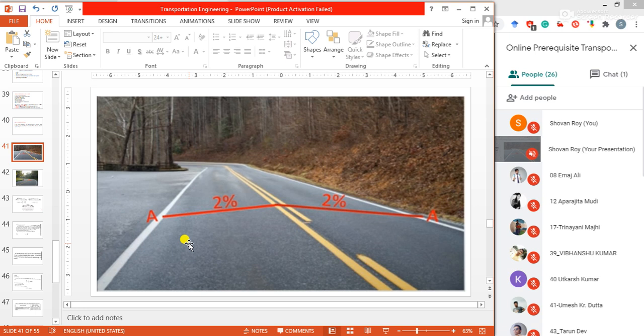So our work is how quickly we can drain off the water from the road surface. This is our main objective during road construction or pavement construction. So to prevent the entry of surface water into the subgrade soil through pavement, because the stability, surface condition and the life of the pavement get adversely affected if the water enters into the subgrade and the soil gets soaked.